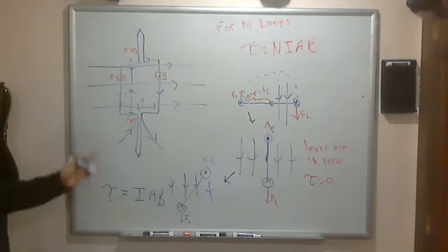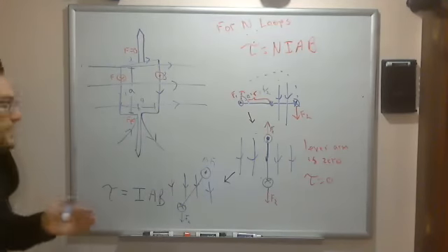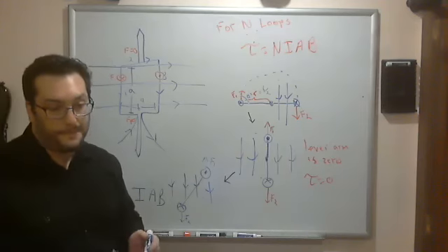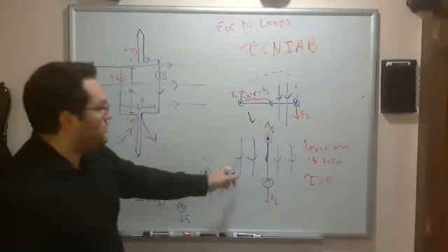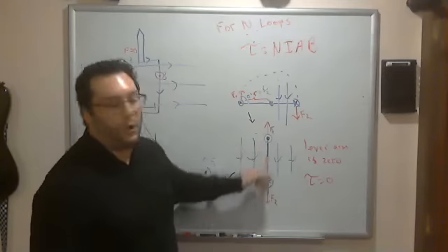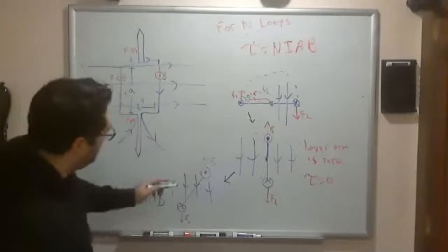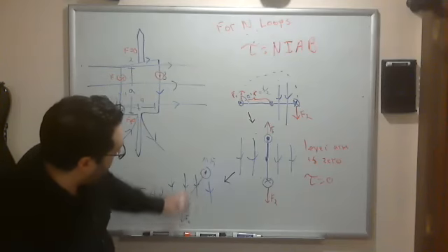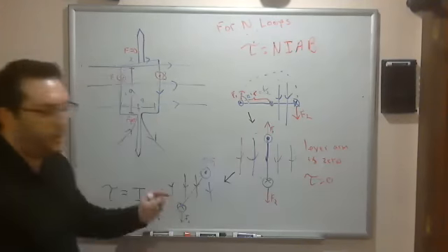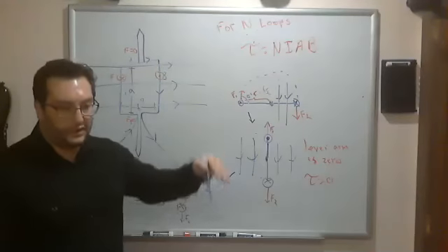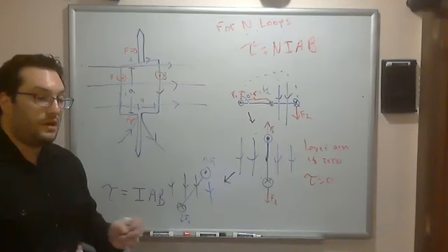Now there's ways to engineer it so that this doesn't happen, right? To make a motor, what you want is, as soon as you reach this point, the force switches. Then the force goes from this direction to downward, right? You want the force to switch once it passes this point to continue the torque in the same direction. So there's ways to engineer this.